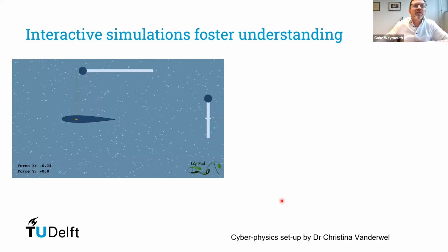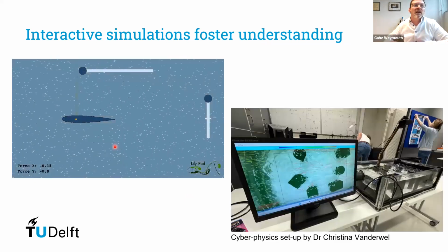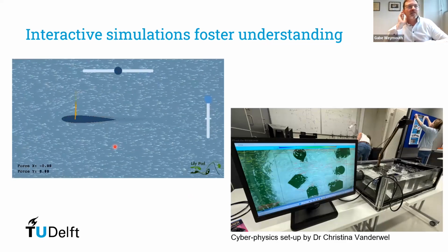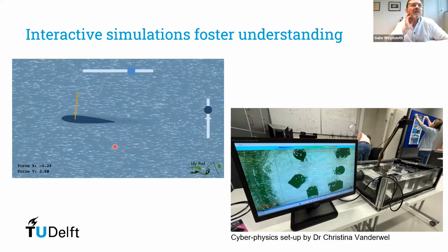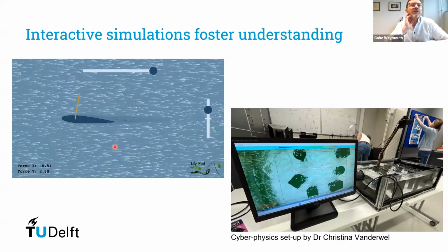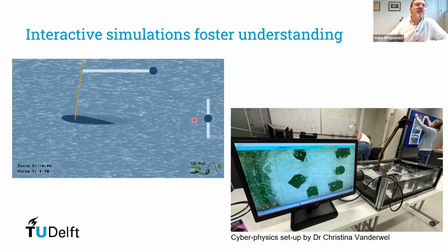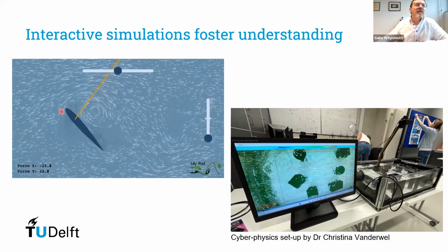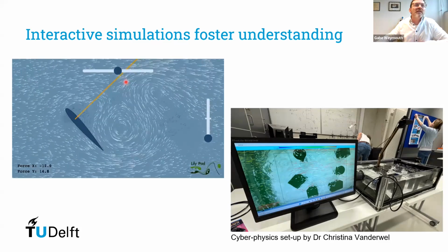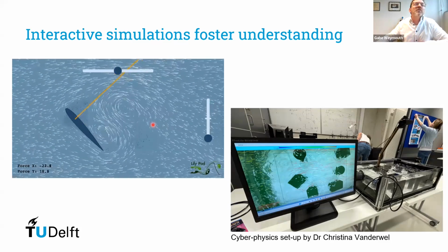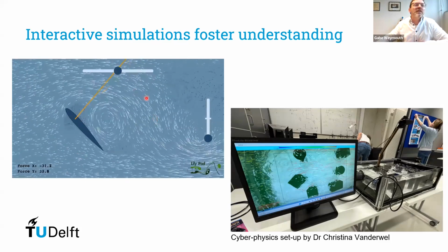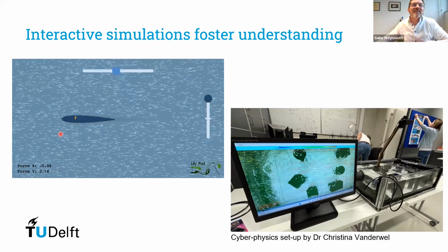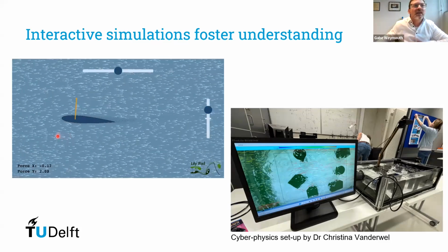So the previous version of this stuff was all 2D, called LilyPad. And I would use this example when teaching all the time. Teaching lifting line theory is great, and something that we do, of course, in class to help understand the basics. But you also want to show that as we increase the angle of attack too far, which I can do by controlling some of these sliders interactively in class, I get leading edge separation and a big wake and my drag force gets enormous. So this is the kind of stall phenomena. And instead of just waving my hands or showing an old video, I can do this interactively. I can give the tool to students and they can do it interactively.